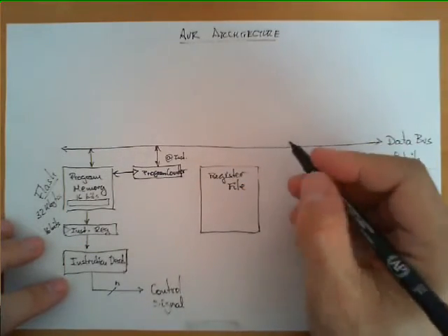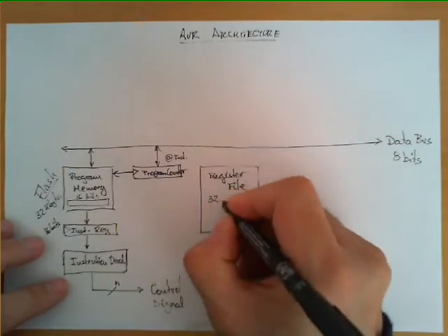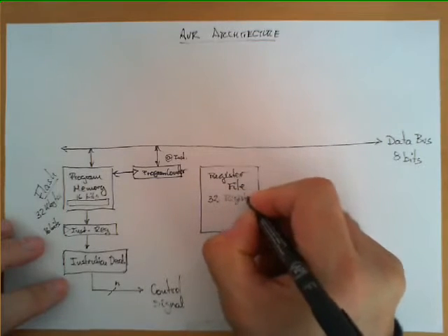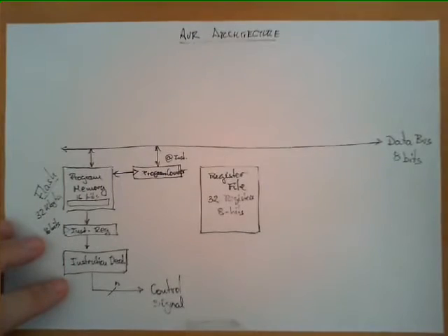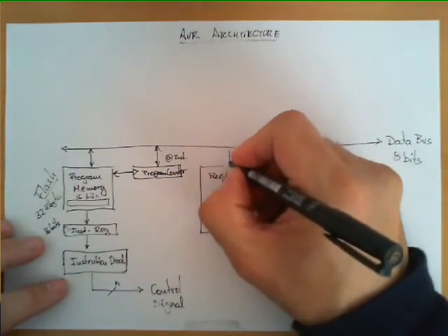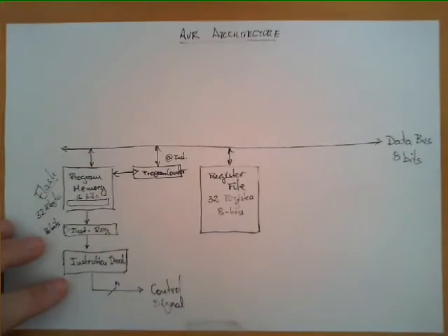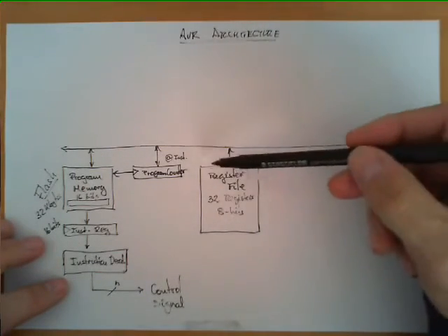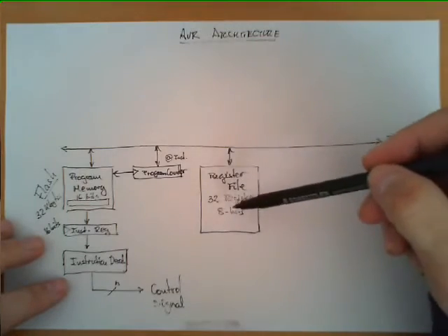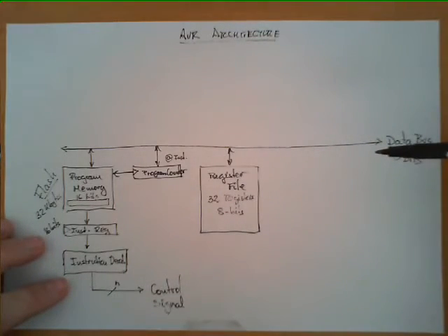Most of the instructions are going to store temporary operands in what we call the register file. The register file is composed of 32 registers, and each one of them has 8 bits. Now, this is where most of the temporary results of the instructions executed by this microcontroller are stored. This block, of course, has a connection to the 8-bit data bus, but the most important connections of this are to see exactly where the data that are stored here go for the execution of different instructions.